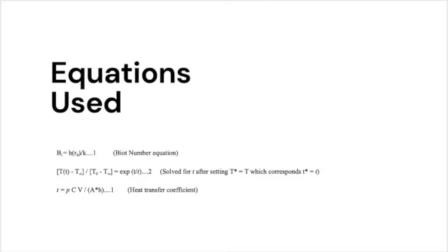The Biot number, in this case, is 0.159. It is a dimensionless ratio of the conduction resistance to the convection and radiation resistances at the surface, and is used to check the validity of the lumped capacitance method. If the Biot number goes above 0.1, then the lumped capacitance method is not applicable for that case. But if it is under 0.1, then it is reasonable to use it.